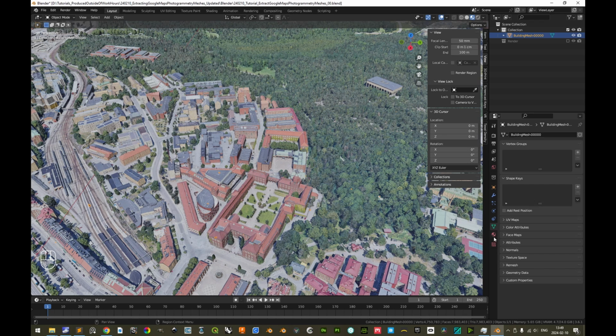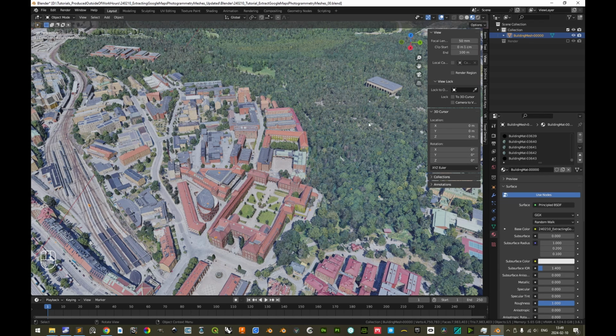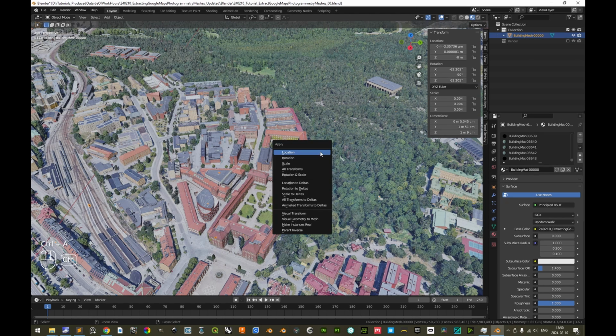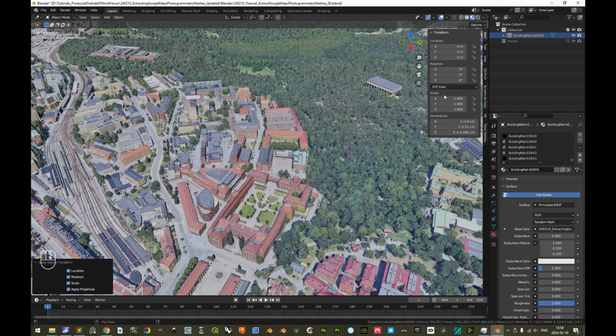Now we want to make sure that all of these 3,644 texture sets are baked down or projected to a separate duplicate copy. Before duplicating and projecting, we should make sure that the transform matrix data for location, rotation and scale, and as you see, all of the sub-matrices have been manipulated. If we have this selected, we'll do Ctrl A and apply all transforms. This makes sure that the transform matrix is reset while all of the transform matrix manipulations have been applied to the object itself.